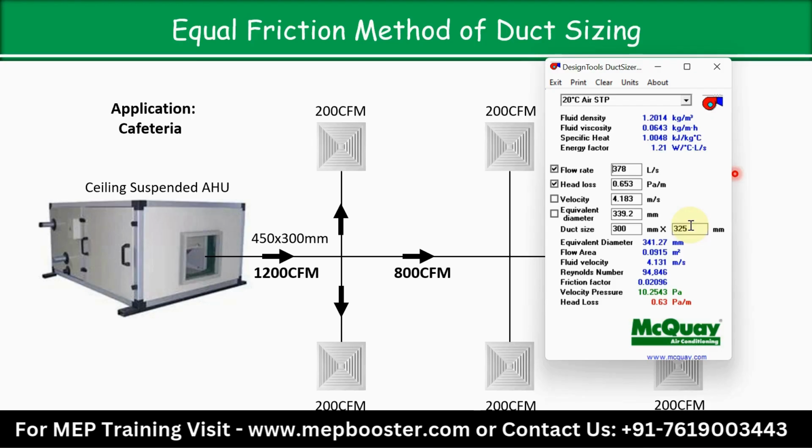Why? The reason is that duct sizes are manufactured in standard dimensions to simplify production and reduce cost. Using standard sizes minimizes material wastage and ensures compatibility with commonly available fittings. For example, if 350 mm is a standard size, it is easier and more economical to use that instead of custom fabricating 325 mm. So if this value comes, just go for 350.